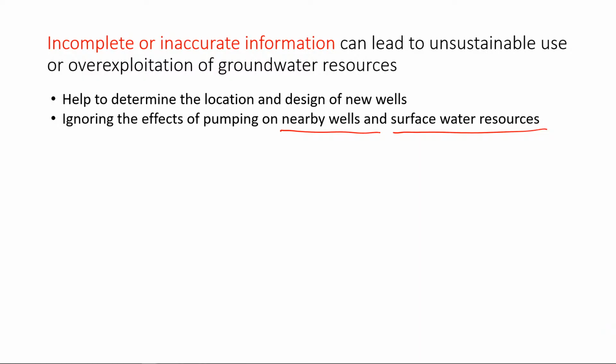Because remember, if you are pumping near a stream, you would be capturing water from that stream. You will not be drawing water from storage, but you will be capturing water from this stream. So your water will be coming from this stream, and your water level drawdown, as we've seen, will remain the same. And this water will be captured from the stream. So in Florida, that's the permitting process, and the water management districts will ask you to show the impact of this well on the nearby wells and surface water resources, and the groundwater dependent ecosystems as well.